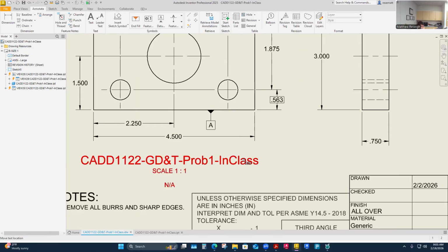And we talked about this a lot in CAD, but once I'm in GD&T and I'm establishing these datums, then those should be where I pull dimensions from, especially locating dimensions. So now I've established A, and this dimension is pulling from datum A. I've established datum A as my control point. This dimension comes from datum A up and locates this hole. And then we have those issues going on with what the tolerance for that would be.